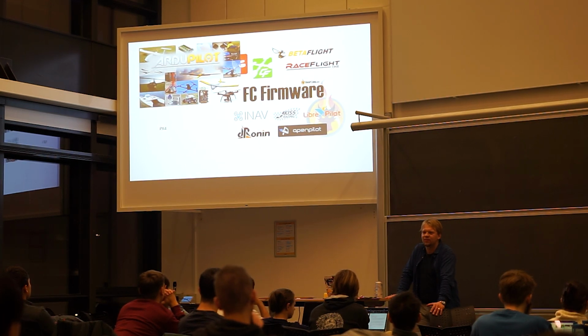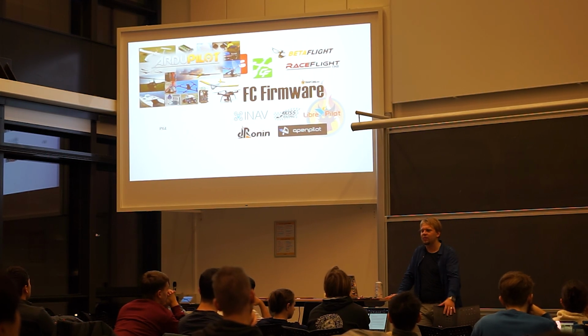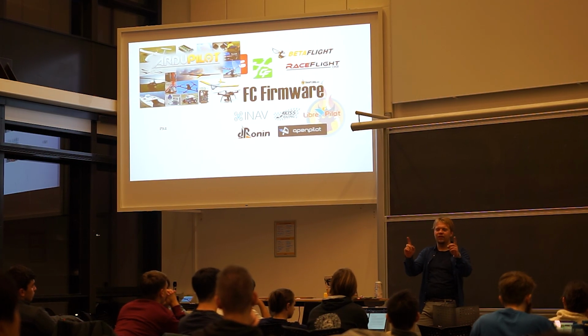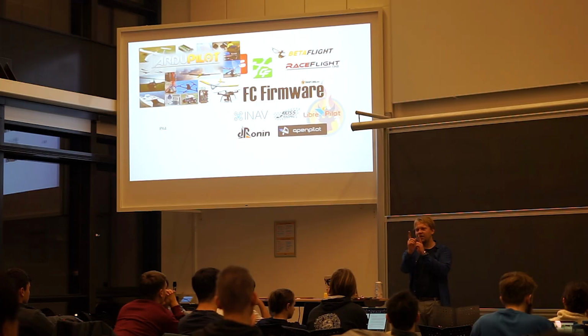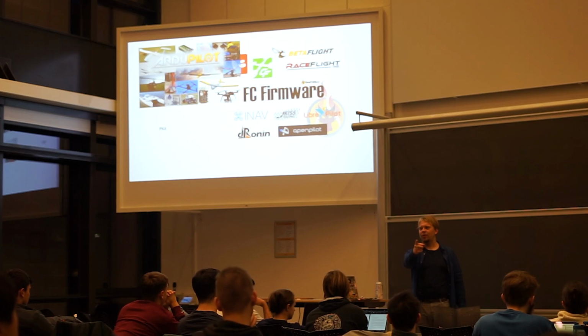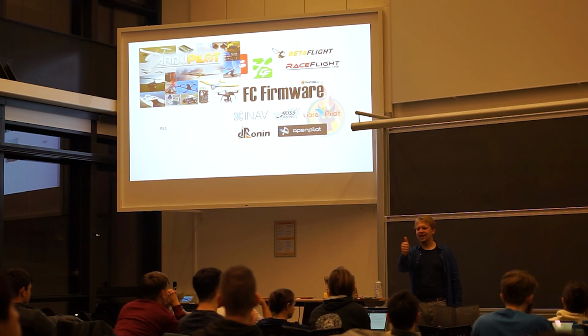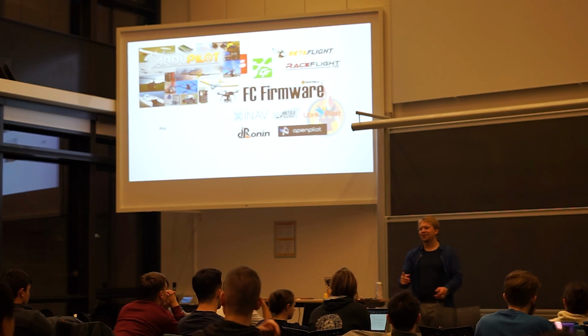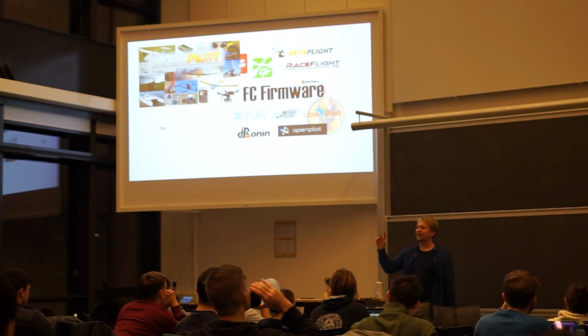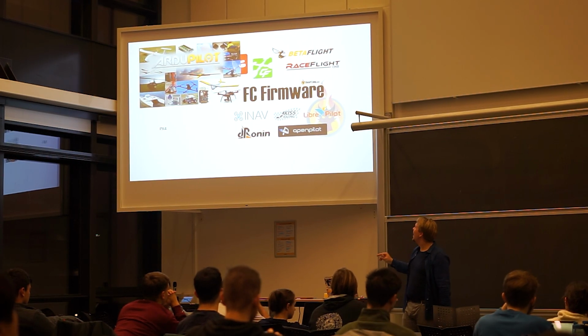The code that was first written for autonomy, for flying to a point, was so bare bones that you literally look at two previous GPS points and make a vector. If that vector points to where we're going, then nice. If not, then you turn left. So that was a GPS recipe. It's actually ridiculous how simple it was, but it worked.